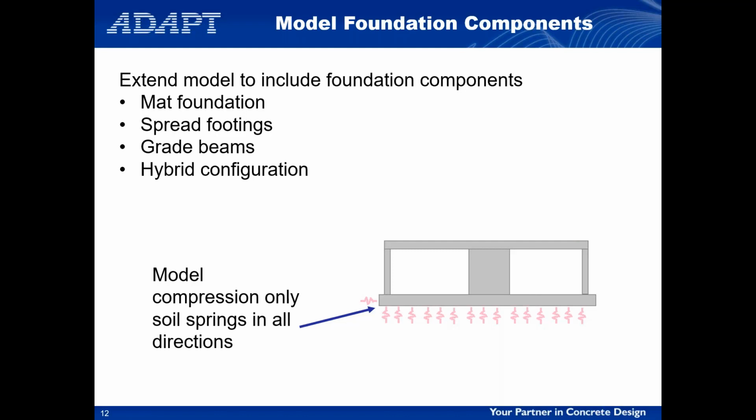So now we're going to move to the foundation, because one of the things that I've heard consistently from our clients out there and just general structural engineers is that if you're just using either Floor Pro or other finite element slab programs, then there's the challenge of how do you take the redistributed loads, right? Because you can't just run an RC slab design, because that doesn't account for the stiffness and redistribution that the post-tensioning offers in your podium.